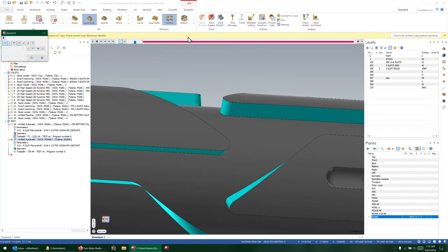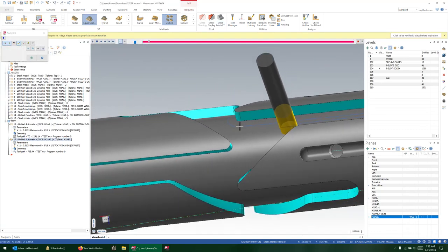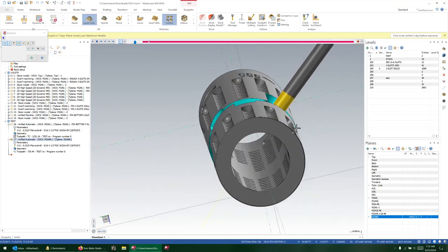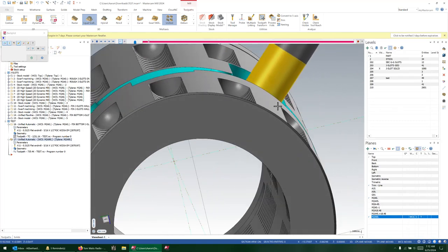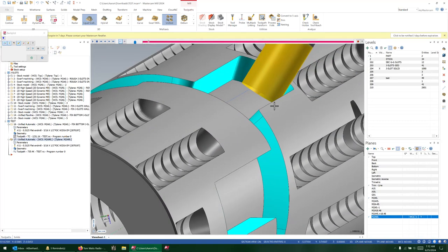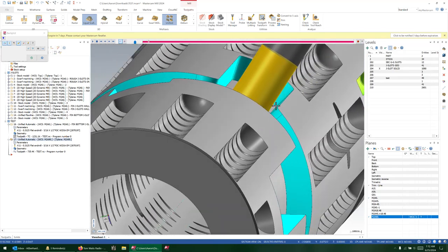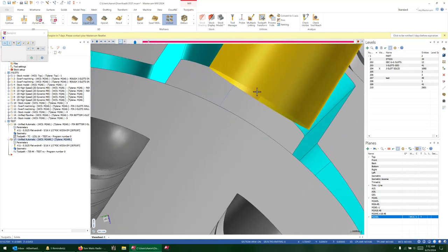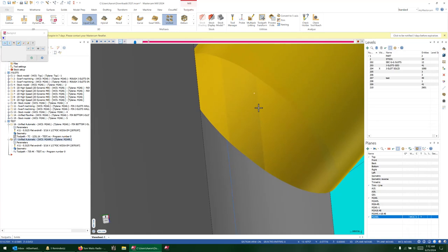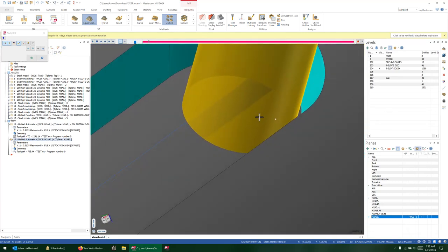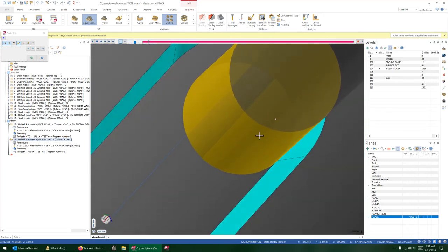All right. So now we've got this toolpath, let's just watch what's going on here. Now you see, this is what I was talking about, where normal to the floor is not swarfing the wall. In fact, I'd probably recommend that we don't actually use a bullnose or a flat end mill to do this shape.